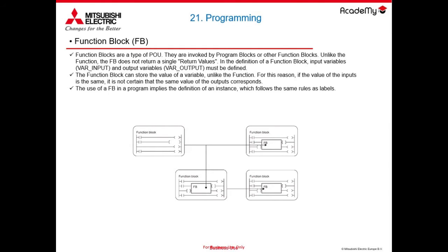Function blocks are called from program blocks or other functions. So you could also encapsulate a function block inside another function block, to make the programming even more structured, let's say. In the definition of a function block, without defining input variables and output variables, the function block can therefore store, unlike the function, the value of a variable.